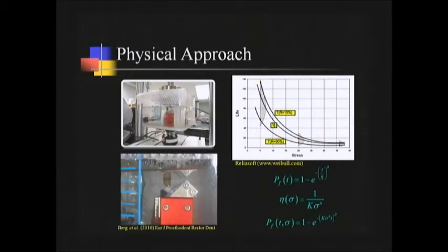So higher bite force than the clinical case so that we observe failure in a shorter time. We're accelerating the fatigue test. And we fit those data to a regression model so that we can try to extrapolate or forecast to the clinical case what will be not only the average lifetime, but what will be the distribution or spread of lifetimes that we can expect to observe.